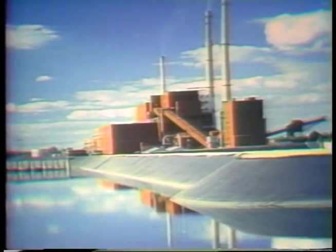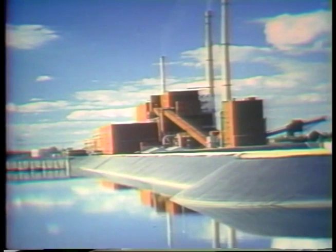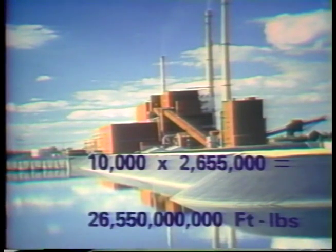Next, we'll convert electrical energy expressed as kilowatt-hours into foot-pounds. Now, there are 2,655,000 foot-pounds in a kilowatt-hour. The unit we'll use in our example generates 10,000 kilowatt-hours. This is the amount of energy produced each hour that the generator operates at full load. Well, 10,000 times 2,655,000 equals 26,550,000,000 foot-pounds of energy.